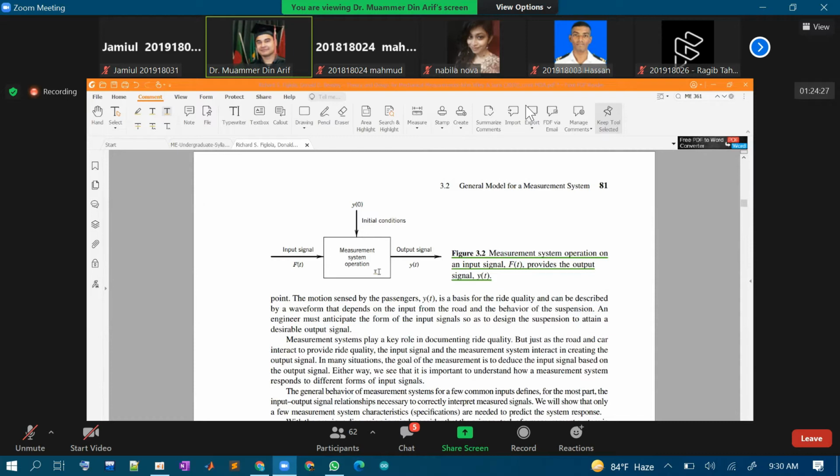If you are going on the road, the ups and downs on the road, the bumps, you don't encounter them continuously. Neither do you encounter them at certain fixed regular intervals. None of this. So how you actually control and how you measure, it depends on measurement, and the measurement has to be dynamic.